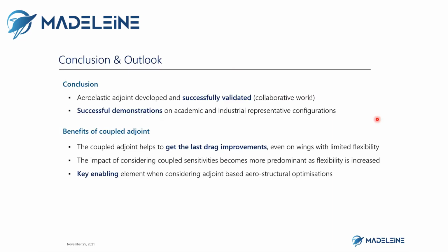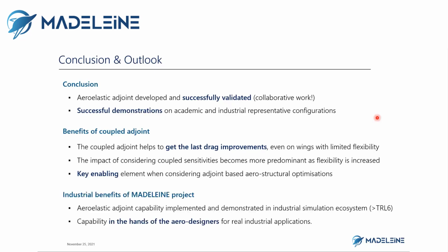What we observe in the benefit of the coupled adjoint is that it really helps you to get the last drag improvement compared to classical rigid optimization. And the impact of considering the coupled sensitivity becomes more and more predominant as the flexibility is increasing. And this is definitely a key enabler for considering MDO problems.